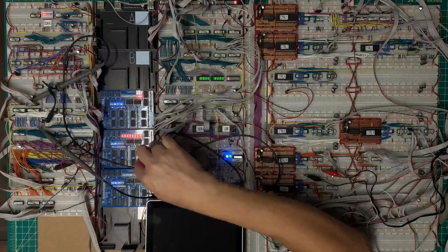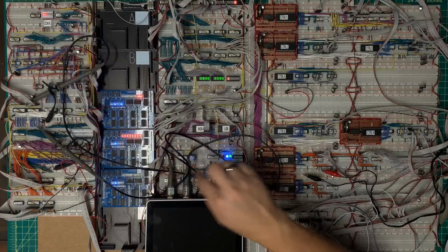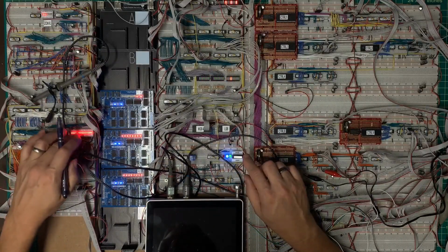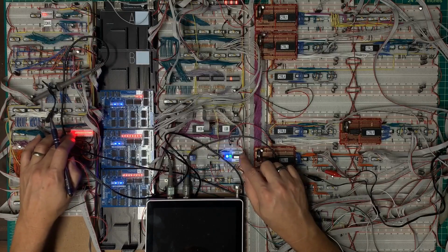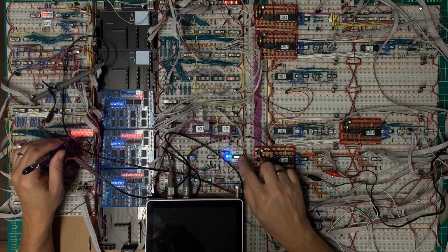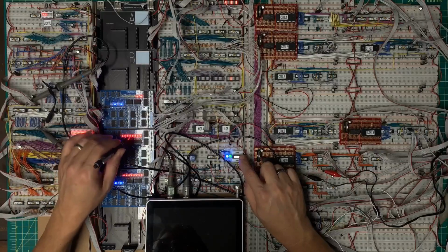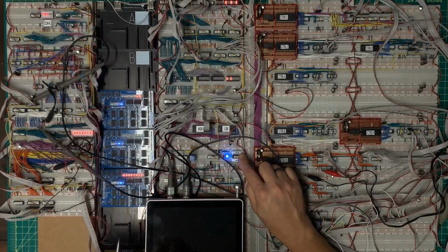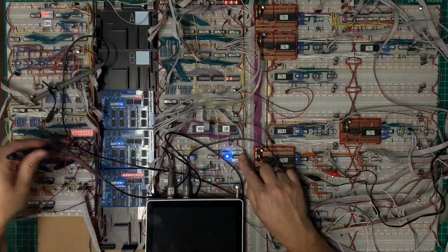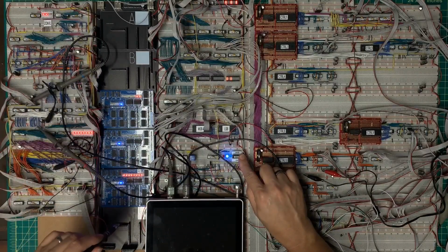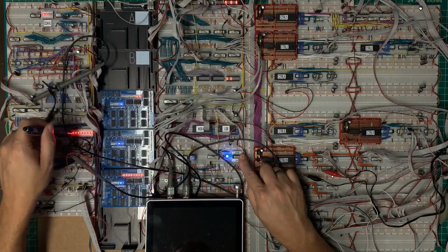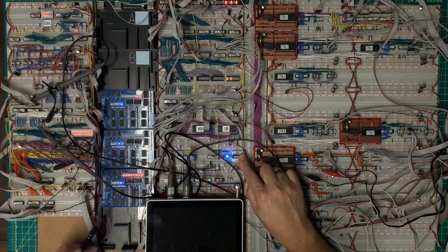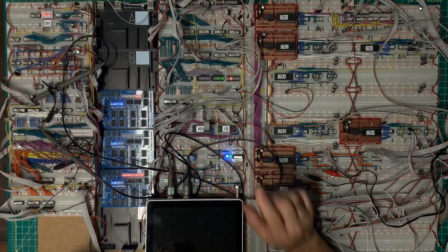I'm moving this value into R2, and again properly forces a no-op up there. Now I've got my add taking place. When I push down on the clock, I am expecting this value to latch in R1, and I'm getting a 0 that's latching there. So I do still have a timing problem related to the ALU and what's latching, and then my contents here have changed to be that of R2, and that's because I'm still pushing R1 out onto the bus.